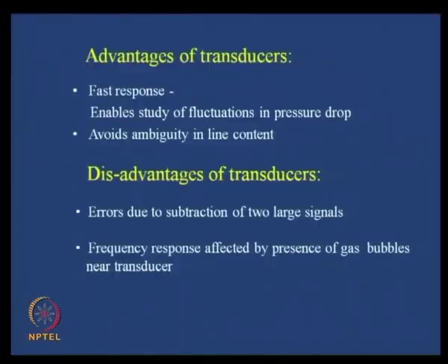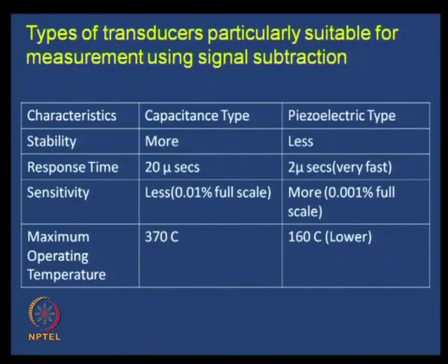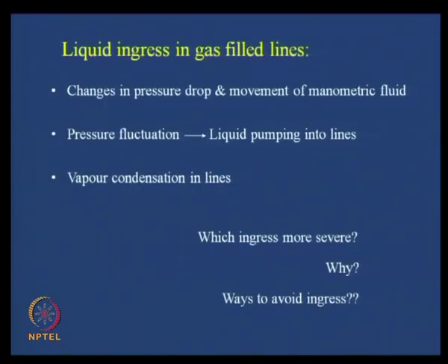The moment we take up differential pressure transducers, again we are having tapping lines, these tapping lines are connected to the two ends or the two sides of a diaphragm. So, therefore, all the problems that were associated with tapping lines, the problems which I have noted down here, all these problems should be there in the case of the differential pressure transducer also.